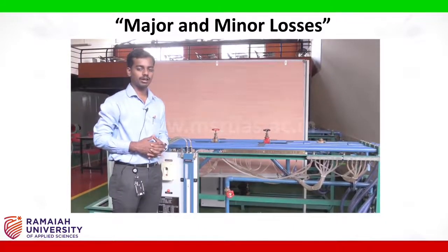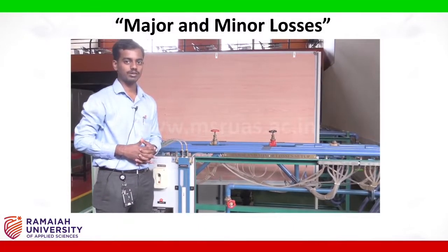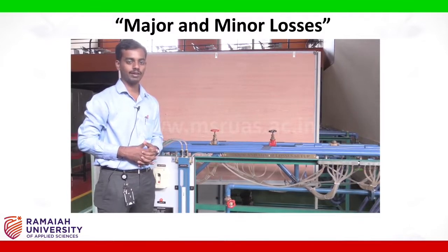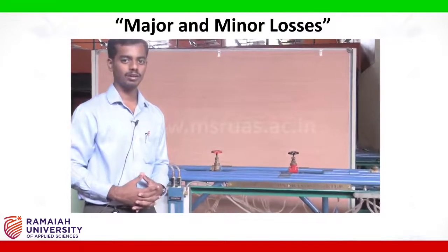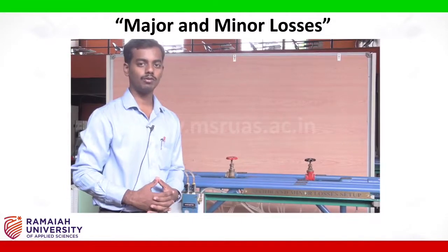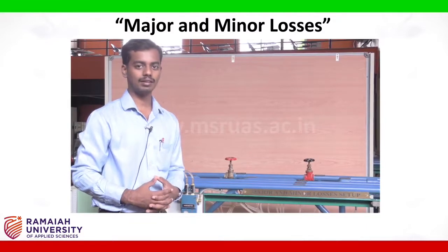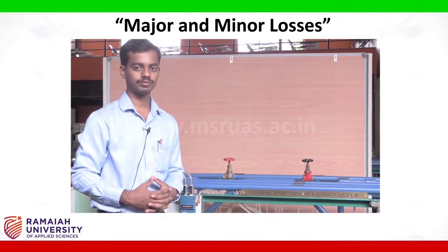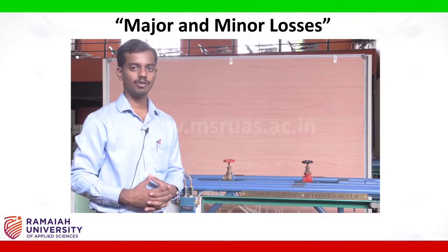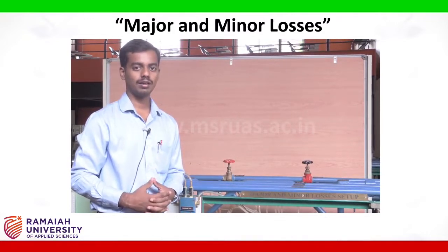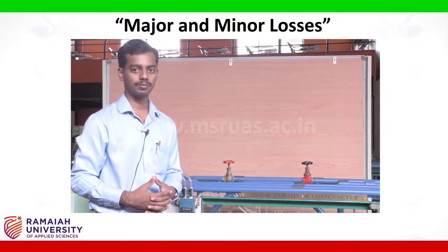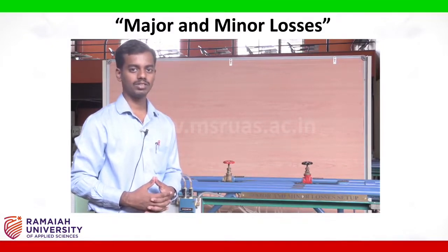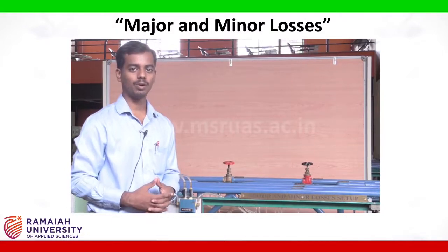Each valve rotation shall reduce the valve opening by close to 30%. The experiment can be repeated for 3 different valve rotations and the data can be compiled. Now we shall move on to the second diameter pipe, that is 3/4 inch diameter pipe. For that, we shall go near the header and open the 3/4 inch diameter pipeline's valve.